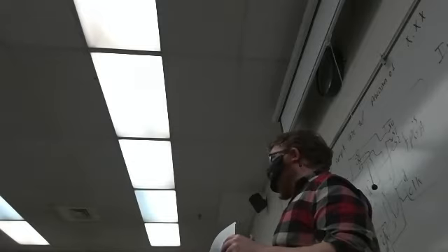Okay, then the next question is, so this one has either 2-wire or 3-wire configurations. You can actually just tie the CS to ground and just ignore chip select. So I would have to specify. So in this next question, in 3-wire mode, what signals the ADC to start a new conversion?